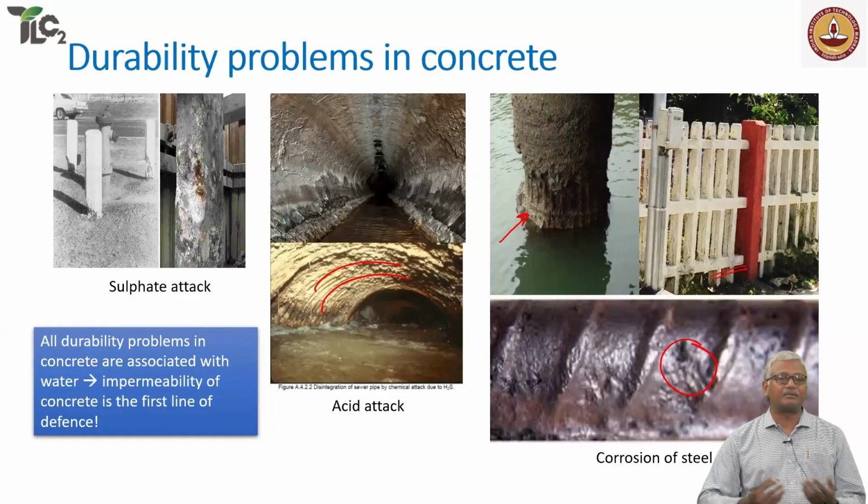It will dry out and get re-wetted, and the presence of water is absolutely impossible to avoid, unless, of course, you are talking about interior concrete elements, in which case direct exposure to water is not really there. But even there, we managed to create all kinds of exposure possible because we have a lot of cracking in the concrete, and especially from toilets, water can get in contact with structural members. And when wet conditions persist, you obviously have an issue of either chemical attack or corrosion in reinforced concrete structures.